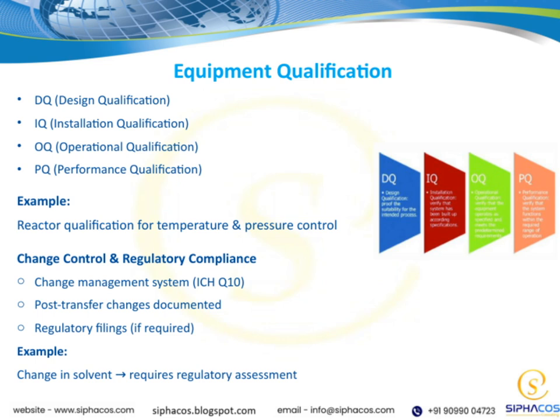our requirements. Then comes operational qualification, OQ, which tests that the equipment operates as intended across its entire range of functions. Finally, we have performance qualification, PQ, where we confirm that the equipment consistently produces the desired results in real-world conditions. All these steps together form a comprehensive approach to validating our equipment, helping us maintain quality and compliance throughout the product lifecycle. This qualification process is a key part of the overall quality management system, ensuring everything functions properly from design through to production.